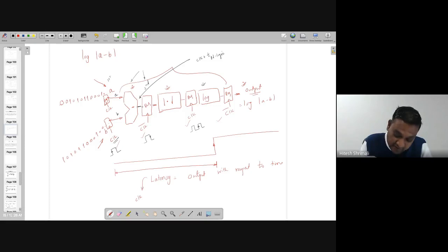So if I have designed the register in such a way that it's working at the clock with the hold time a little bit higher than what is here, then this data is transparent for this register. So it's not a correct way to take the clock. It's better to take the clock bar so that it saves the clock, as well as it will not allow this data to pass. This data will be passed when the next clock is coming on the negative side.